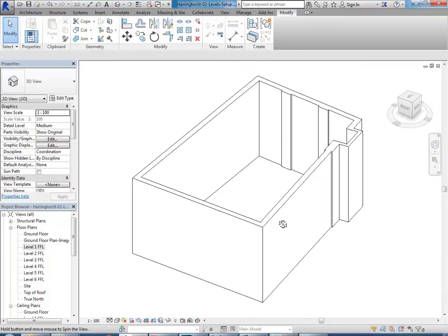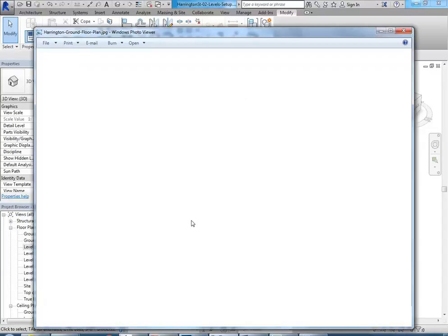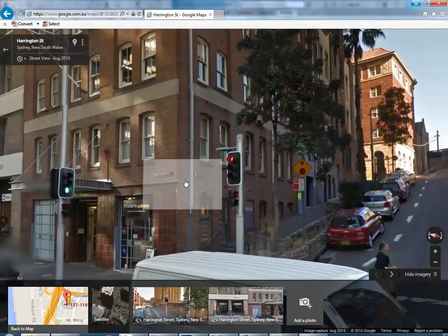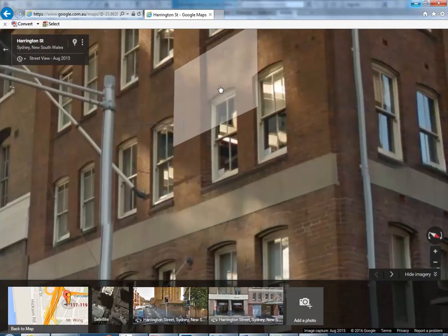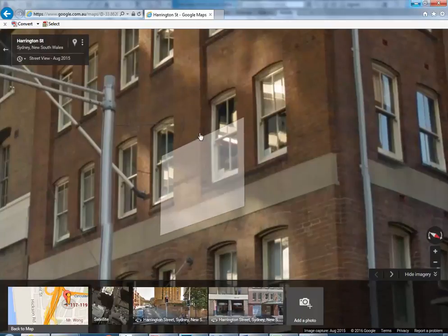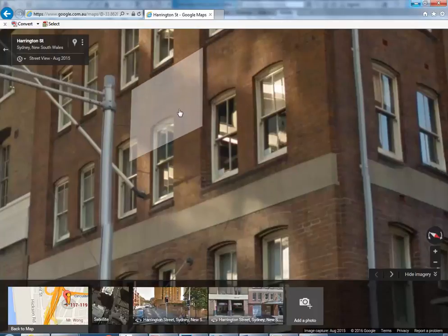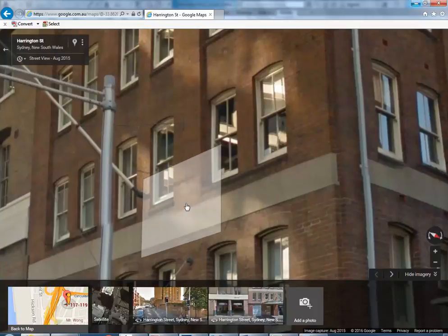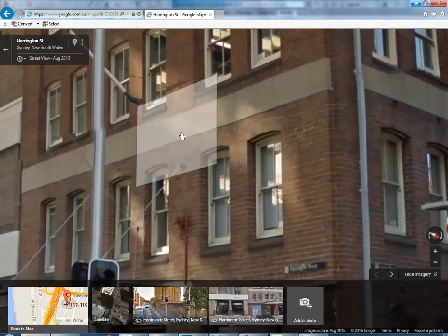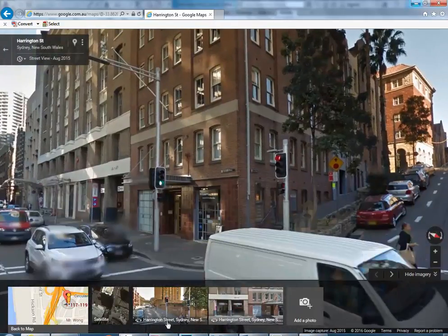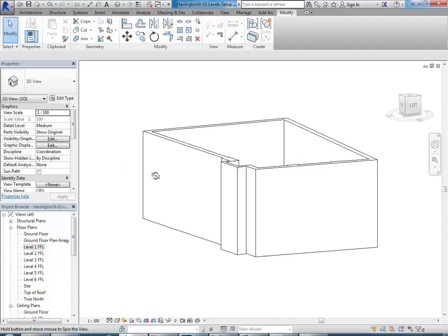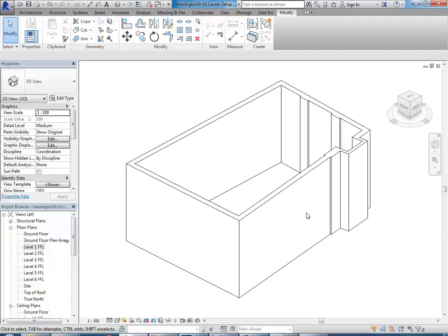Okay, so then when you go to do the upper levels, above level 2, try to keep the inside face of these walls in line or flush, and then you can have the piers done with a different wall thickness so that they line up with the outside. So that's why, if you're wondering, I stopped the walls there, because you will need to break the walls up a bit differently on those upper levels. Right, so anyhow, if you set it up the right way, it shouldn't take you too long to get all of the outer walls done.